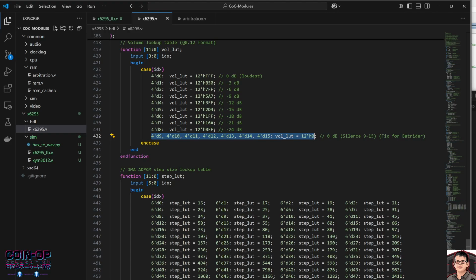But ultimately, when you're doing video, let's say you're trying to output a video frame, if you're taking a line buffer approach, you must output the successive line by the time H blank reaches the next H blank. So by the time you start the horizontal blanking interval, if you're not able to output the next successive line by the time the next horizontal blanking interval occurs, then you're in trouble, right? The same thing is true with vsync, right?